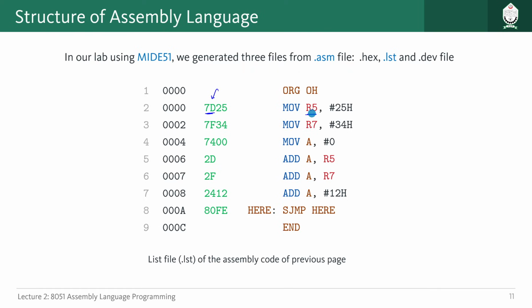In this way, it understands two things: what the instruction is, and also the size of that instruction, which is 2 bytes. Because it knows the length of the instruction, it can increment the program counter accordingly. For this case, the program counter should increment by 2 for the next instruction.